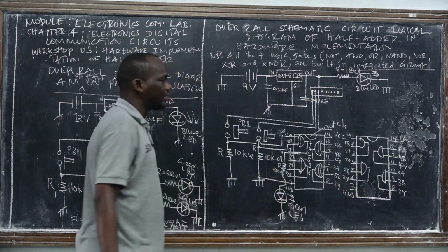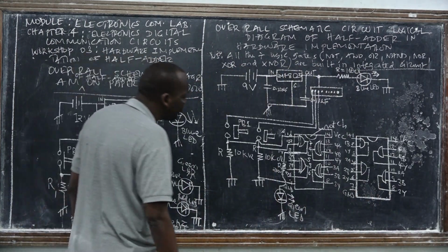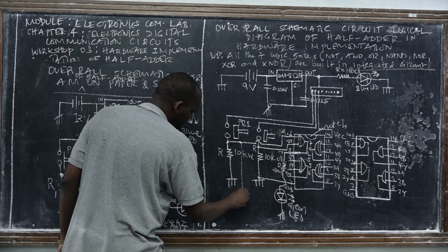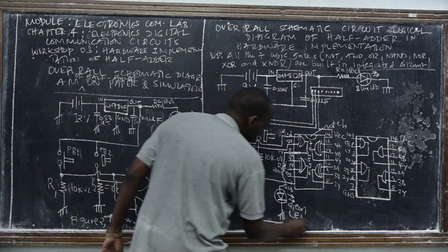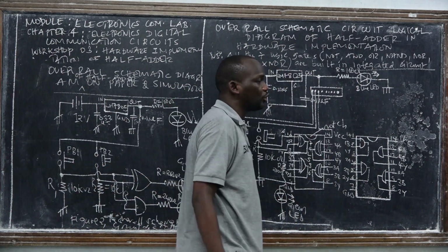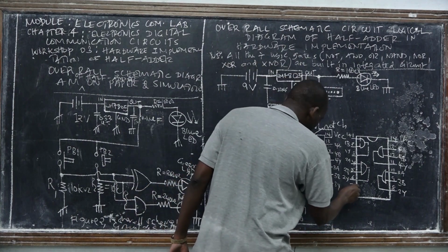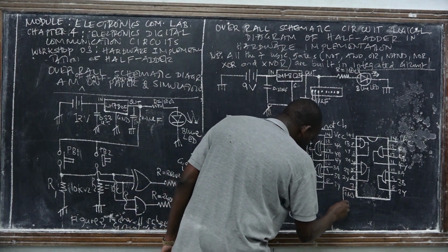So we just take a jumper, we can use a copper wire, then we take this input. First of all, we have to connect it to power. Remember that. We have to connect it to ground. So this one should be connected to the ground, common ground.